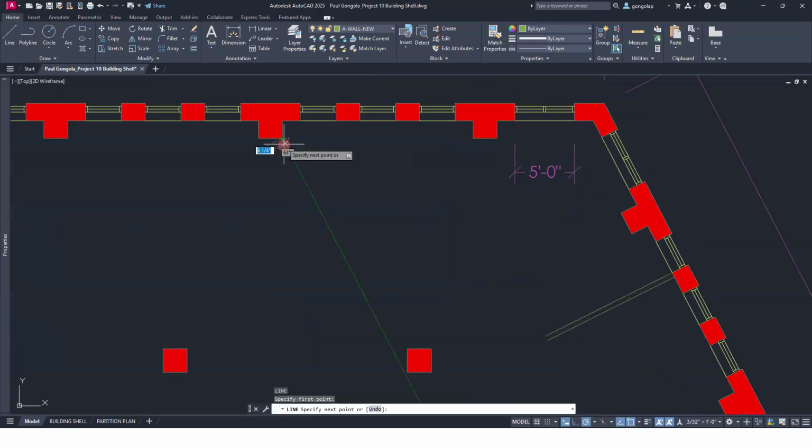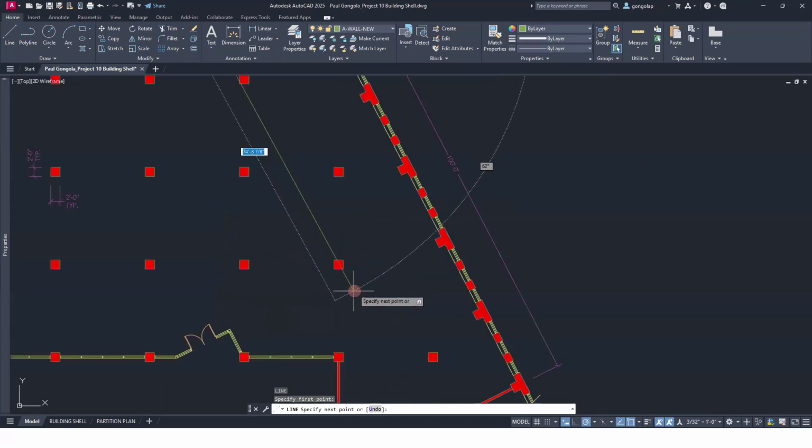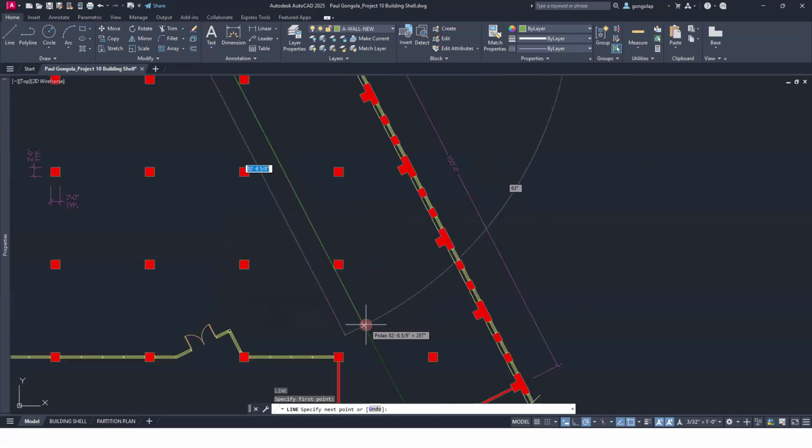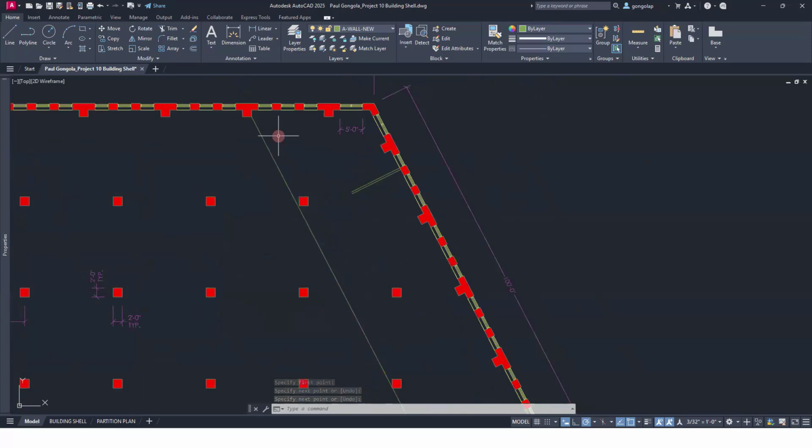I'm going to draw this line. Again, I am looking for that 297 degree angle, not the 63-degree angle, but the one near my cursor, where mine is saying polar 9 feet 8 3/8 of an inch, and then the angle symbol, and it says 297 degrees. So I'm going to just draw a big old line. Make sure that you're on that 297 degrees. All right, and I will offset this also 5 inches.